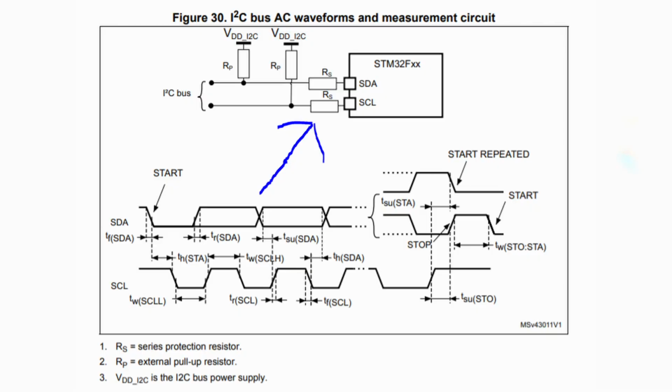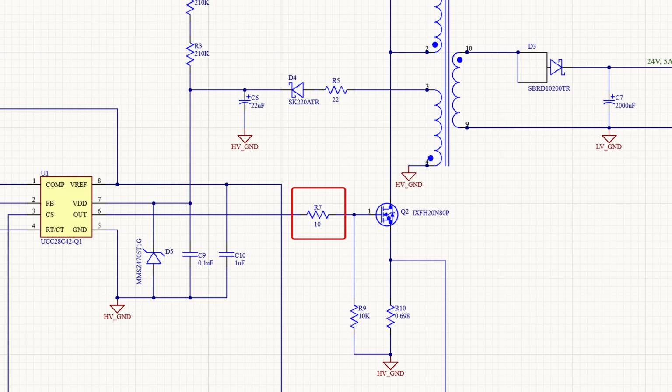So now I'm sure you must be wondering, how can we control the rise time and fall time of our digital signals? The short answer is by simply using a resistor that goes in series with our periodic signal. You may have seen these resistors in various types of digital circuits, such as digital communication lines, clock lines, and the gate pins of power transistors. We will actually cover the way to appropriately size and calculate the values for these series resistors in another video. But the general takeaway here is that a higher resistance equals a longer rise time, which therefore results in better radiated emissions.